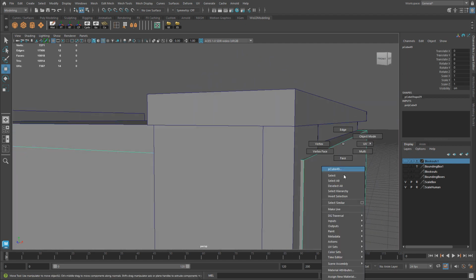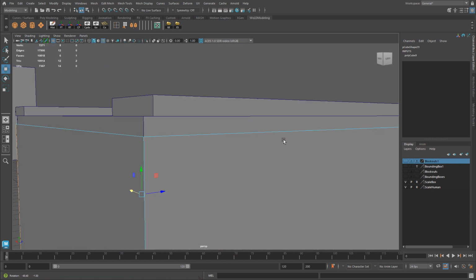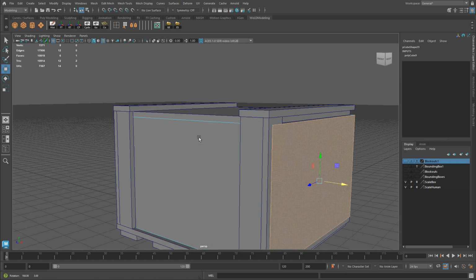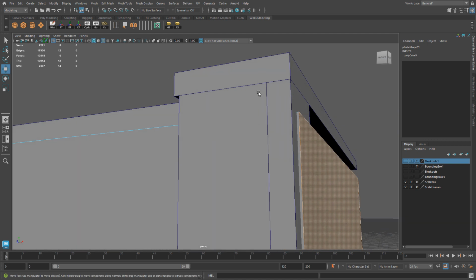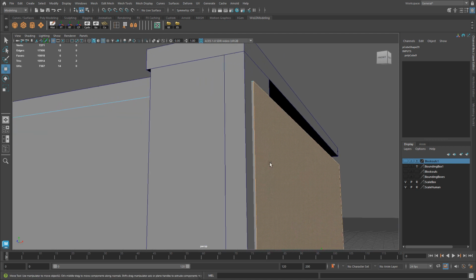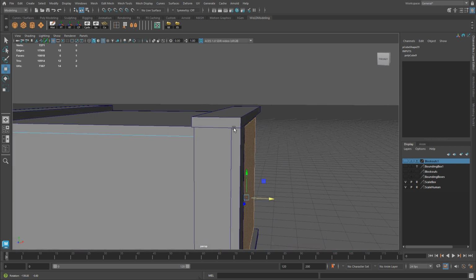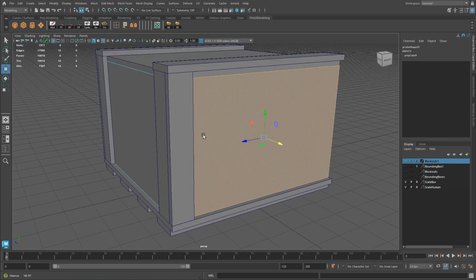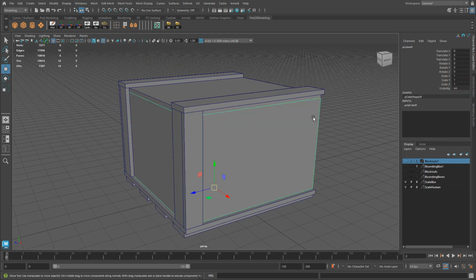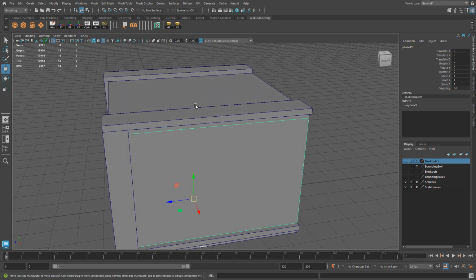And then let's also modify this one. This one just needs to be snapped. I'm just checking the other side. Yep, just needs to be snapped to this vertex as well. So I'm going to highlight that axis, the x-axis, hold V, middle mouse click and drag on this vertex, snapped. All right, so that side is done. Let's repeat it for the other side. We just have 4 planks to go, and then we have 1 plank at the top.